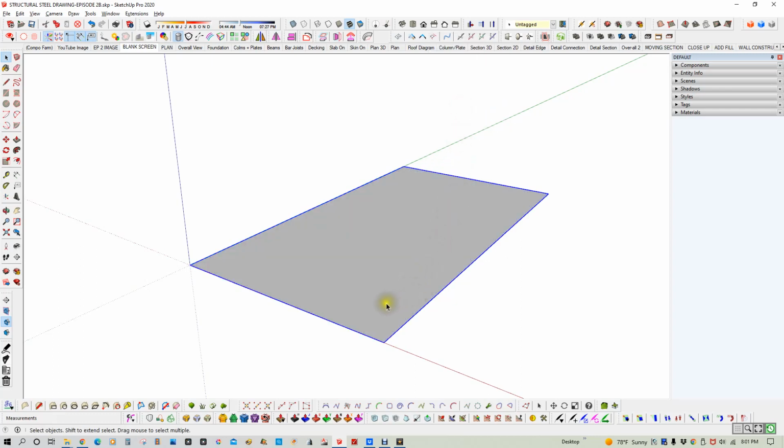And I want to take and divide this into a 3-compartment grid by a 2-compartment grid. So I'll go ahead and make sure, and I'm just going to draw lines. Midpoint and group, this is going to be dividing in half, so these should both be 16 feet. I'll just take the tape measure and check it. Yes. Okay, and going the opposite direction, we're going to take and do a guideline at 20 feet and another one at 20 feet.